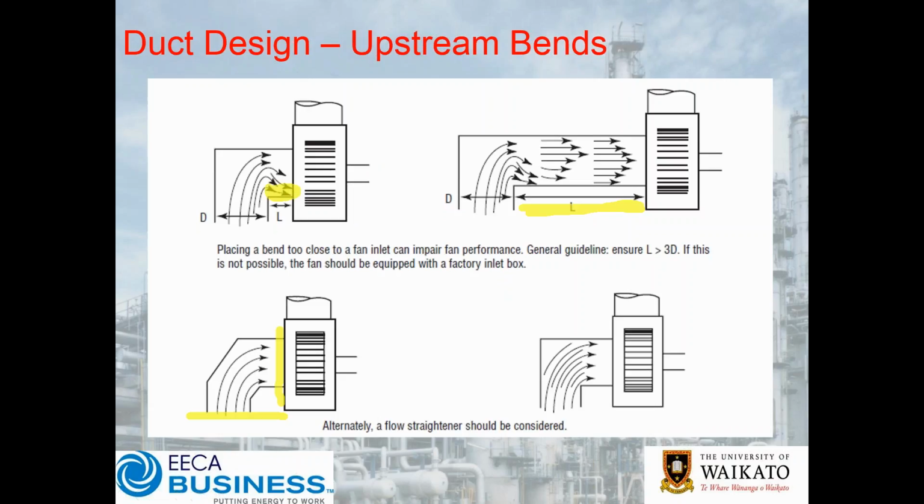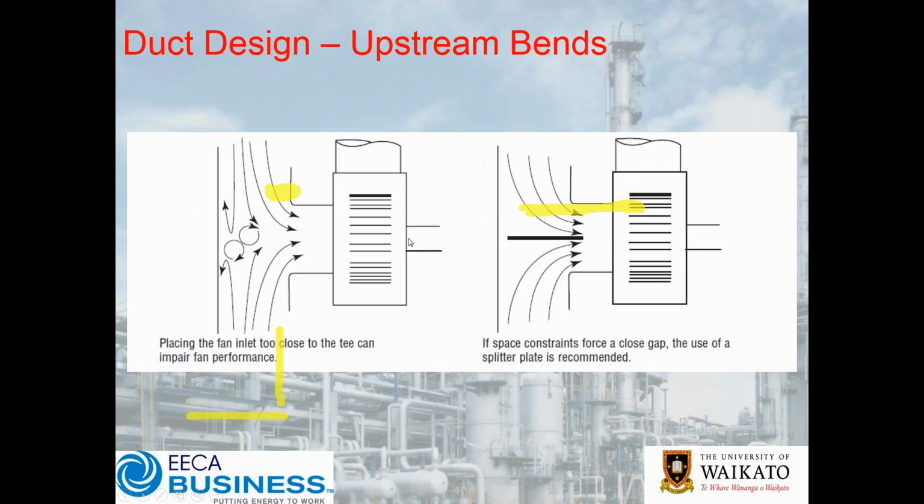So as the fan impeller is rotating around past that point, the blades are going to start to stall, and then as it turns a little further it suddenly gets a whole heap of air, and so you're going to get all sorts of nasty imbalances on your impeller. The fan's going to run a little bit rough. It's going to put all sorts of vibration back down through your shaft. Depending on your bearings and what sort of condition they are in, it can start to cause all sorts of trouble for you. Let me just clear those scribbles.